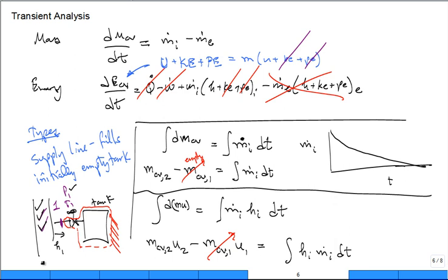You made the great observation. So if it doesn't vary with time, it's a constant with respect to time, you can pull it outside that integral. True? Once you do that, I recognize what this is, the integral of m dot dt. So this whole side becomes the enthalpy, which is constant coming in, times the final mass in the control volume from the mass balance.